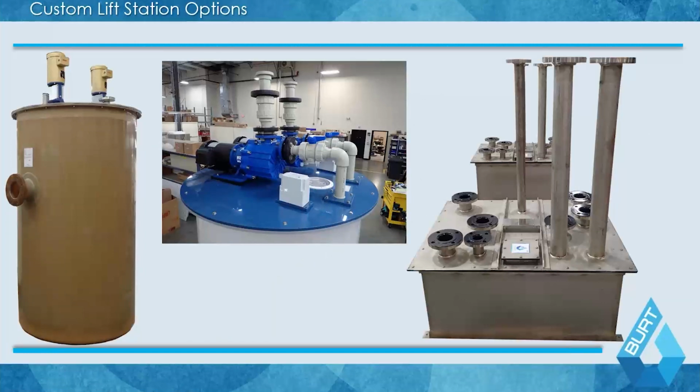Again, this is like the cell priming design. These are lined tanks, obviously for higher strength chemicals, fiberglass for high temperature, if you have things like steam condensate, for example, coming in as part of your drainage system. The other option, which I don't recommend, is if you have to bury the tank to the rim. You cannot do it out of thermoplastic. You have to do it out of fiberglass or metal. You do not direct bury chemical lift stations.